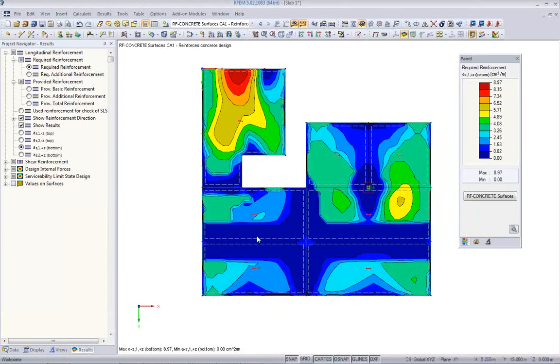We see here now the direction longitudinal to the beam takes out the design pretty much of this reinforcement where we have defined the beam. So RFEM knows that there was 1.60 meters left and right of this beam, and this section will be part of the beam design.